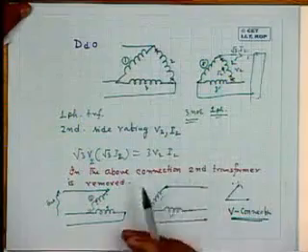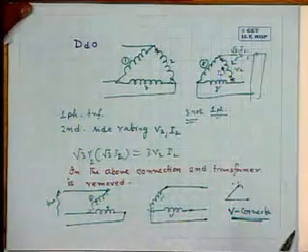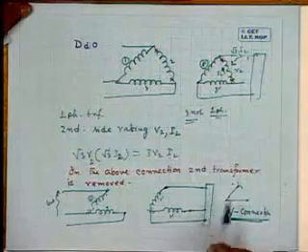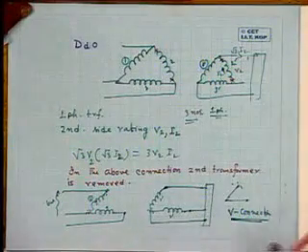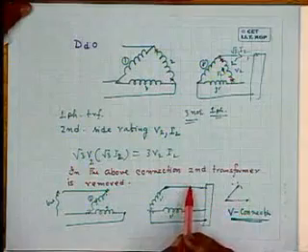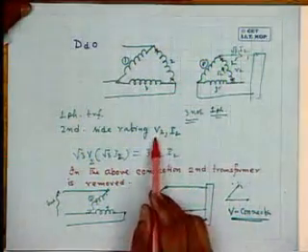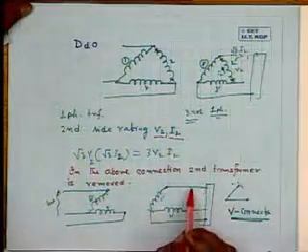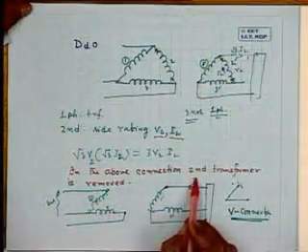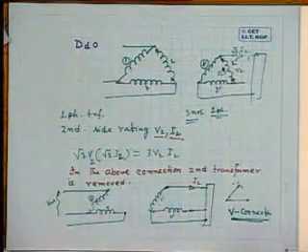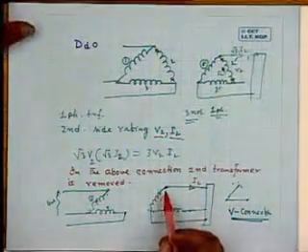Now let us try to estimate what will be the kVA output of this particular VV connection. Suppose you connect a balanced three-phase load here. Tell me what line current you will allow to flow on this side. Rating is known, V2, I2. I2 only, because this current is the same as the winding current.